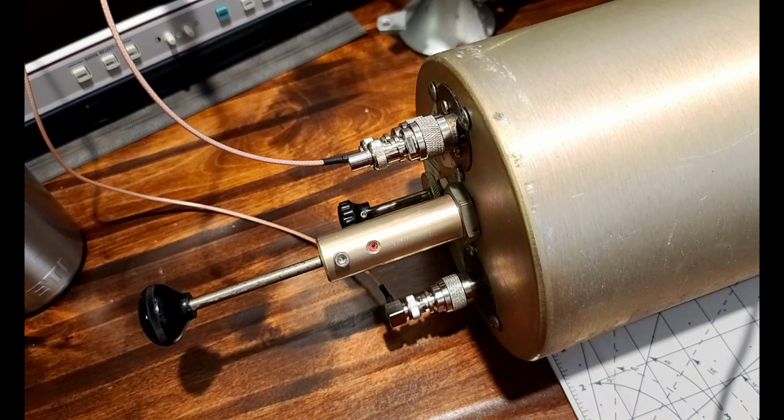We also made sure that the frequency band pass was quite narrow, so that we tried to contain or curtail what passes through the filter and what gets rejected. We tried to make sure that the resonant frequency of the cavity filter was 144.39, and we did our best to zoom in on the frequency response graph, so that we are right at that 144.39 meeting point, which is fine. I think that's a good way for tuning a cavity filter.